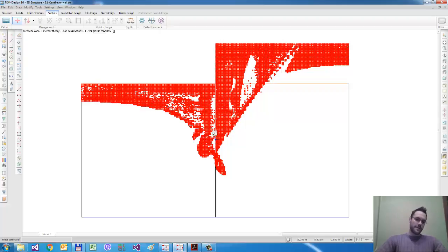So the slip surface somewhere here, according to the passive earth pressure, is 45 minus half of the friction angle. So it's almost what we have with the hand calculation, but we have a mixed zone here because the rotational point is not at the bottom of this wall, because if the rotation point were at the bottom point, there wouldn't be any equilibrium state in this wall.